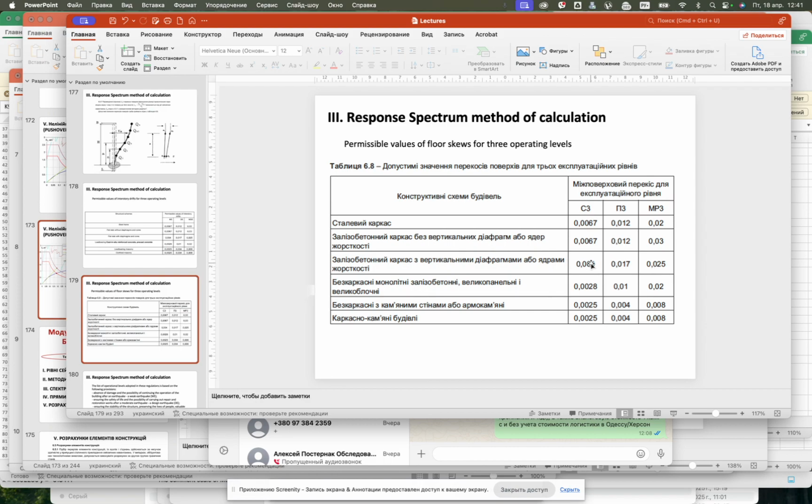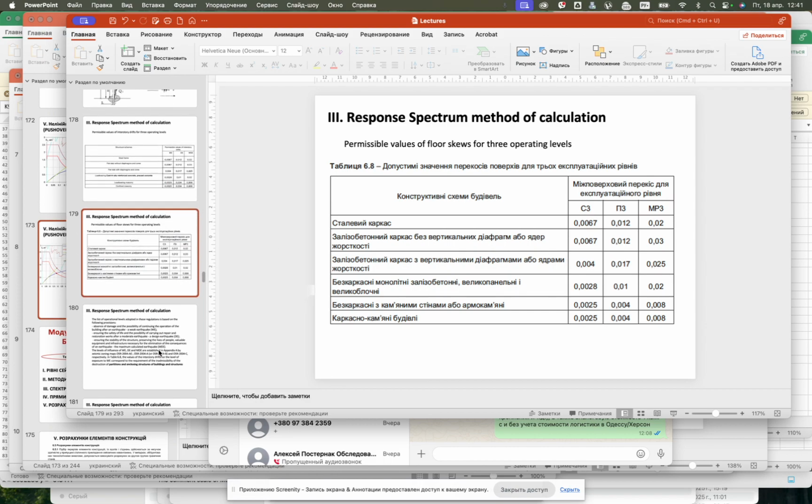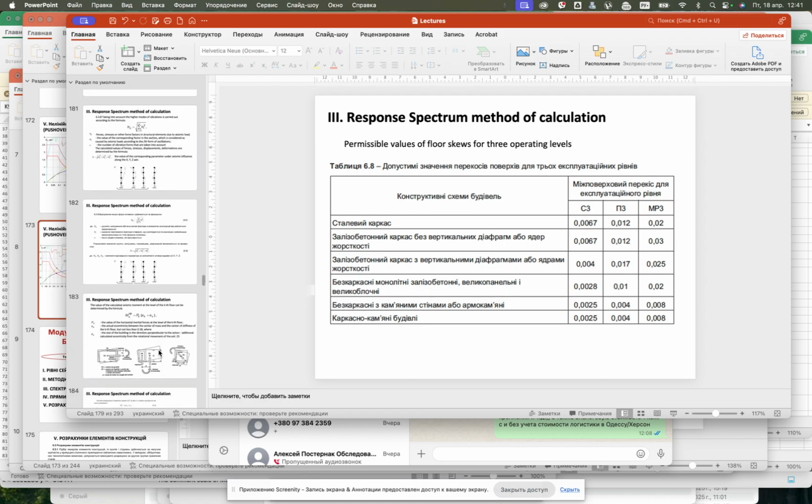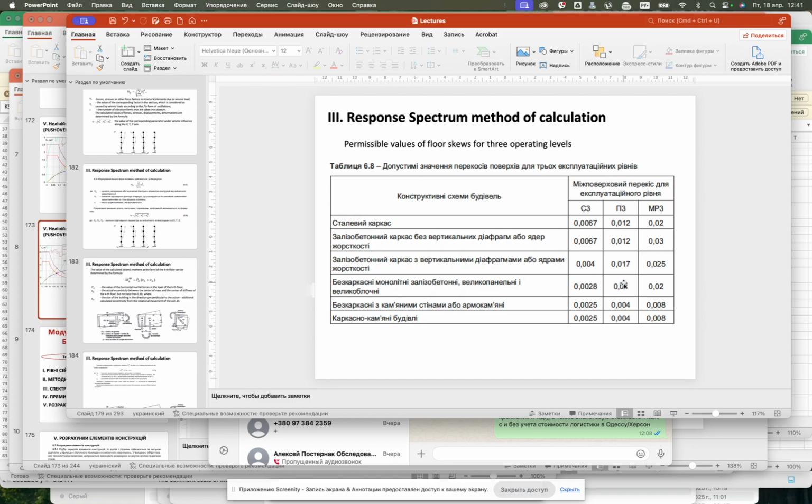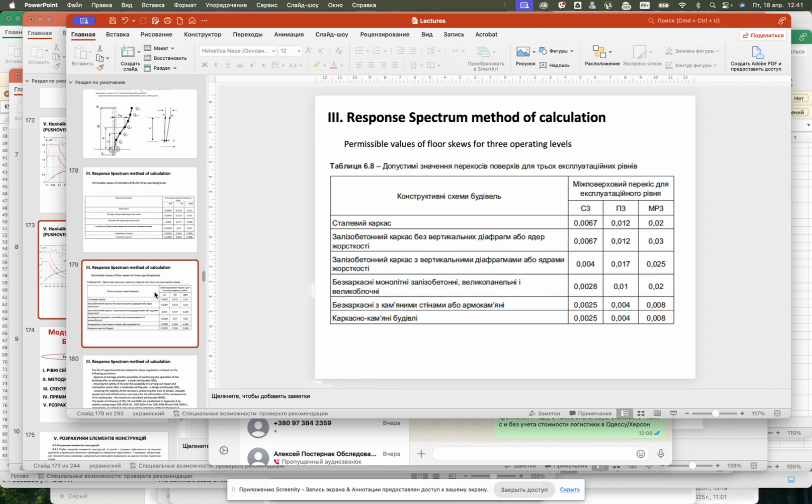So we have minimum displacement, which means weak earthquake, and we also have design earthquake, which means bigger displacement, because after this earthquake we can make the capital repair or the current repair of the building, and maximum design earthquake, according to which we will get complete destruction of the building after the earthquake. And one more slide I will give you.